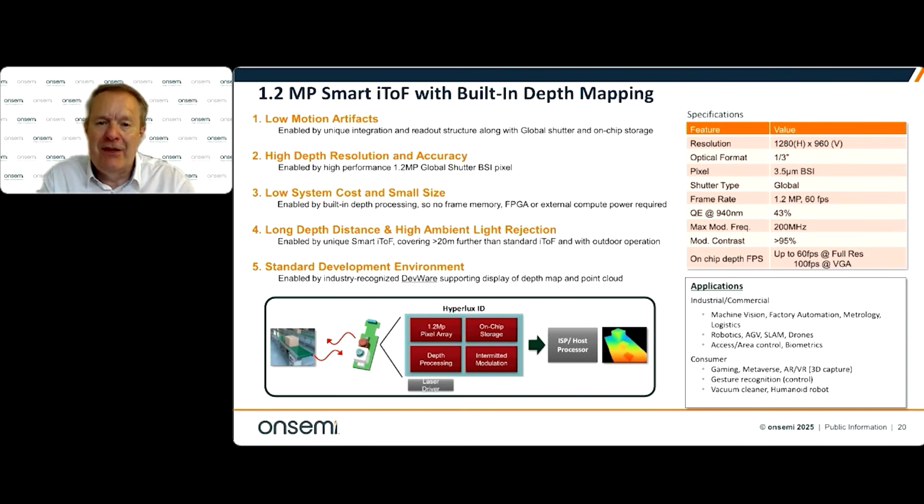iToF Hyperlux ID also works in a standard DevWare environment. So you can do exact pixel evaluation, and you can get the depth map, point cloud, and confidence, all available through that DevWare interface. So applications, we talked about machine vision, factory automation, metrology as well.